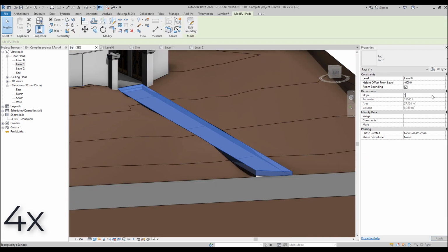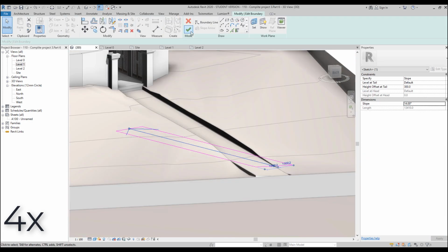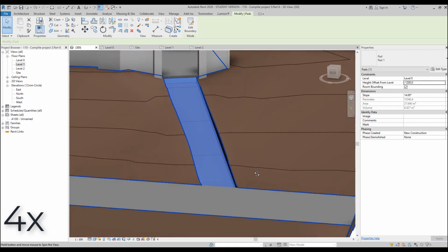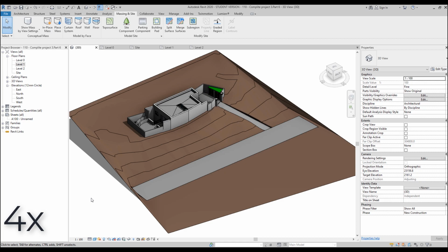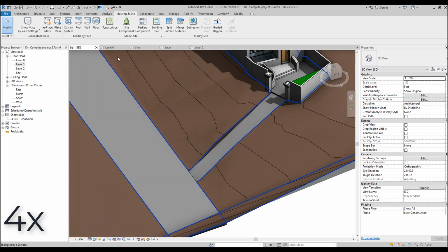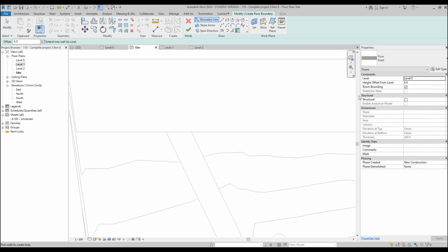Now we should check our entrance road again, because we changed the slope, and that's why we get a problem again. So everything is the same, just go to the Toposurface, change points, elevation, and that's it. And do it until you get a nice result.